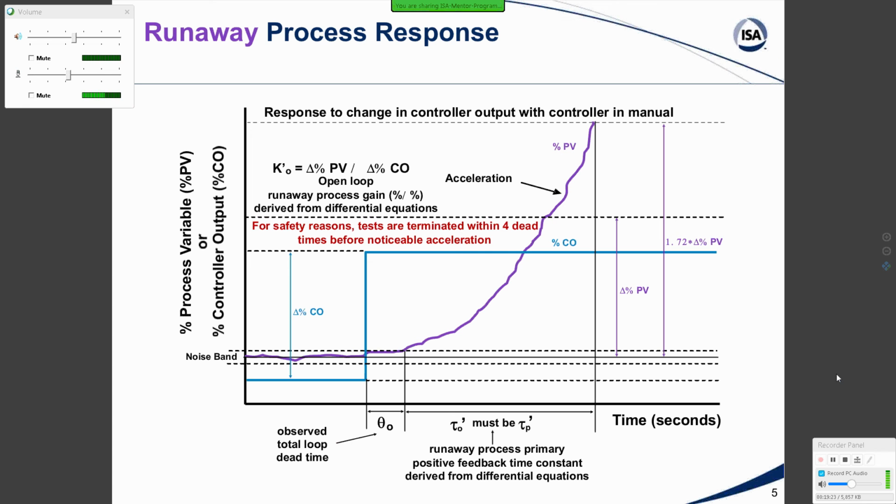that will show when you get into a reaction rate heat release that's a function of temperature that exceeds the cooling capability and causes a positive feedback action, and you can actually estimate. And in fact, that's the only way really of getting an idea. You can't measure this online. The only thing you can do is from the ordinary differential equations estimate what it is based on first principles.